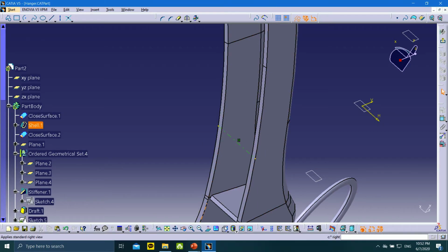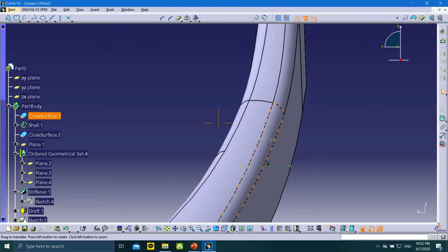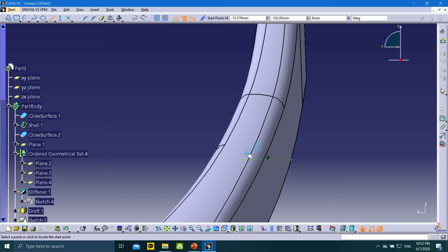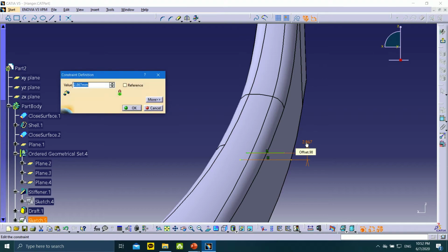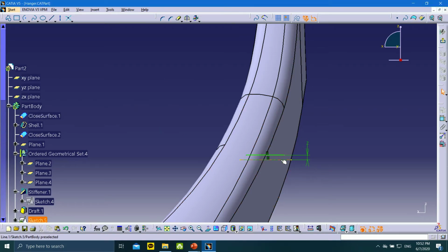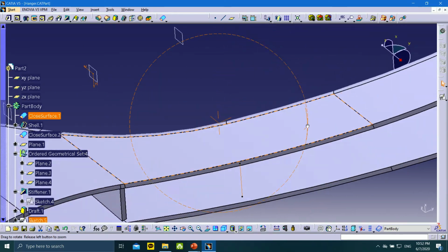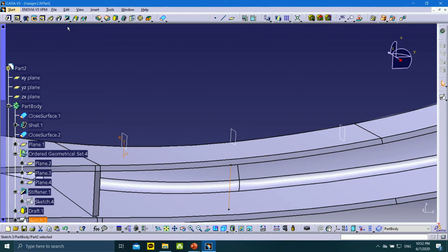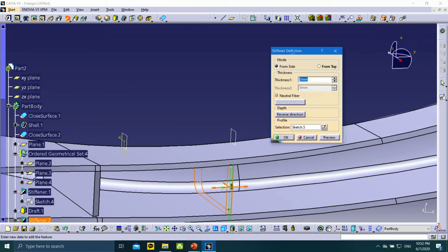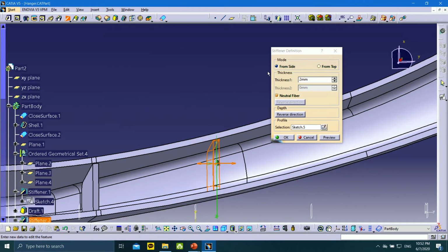Okay, go to right view. You can draw any, sorry, this one not construction, any line in here, something like this. Don't care about dimension, and just exit the workbench, and in here we create another stiffener. Select stiffener, with the same dimension.